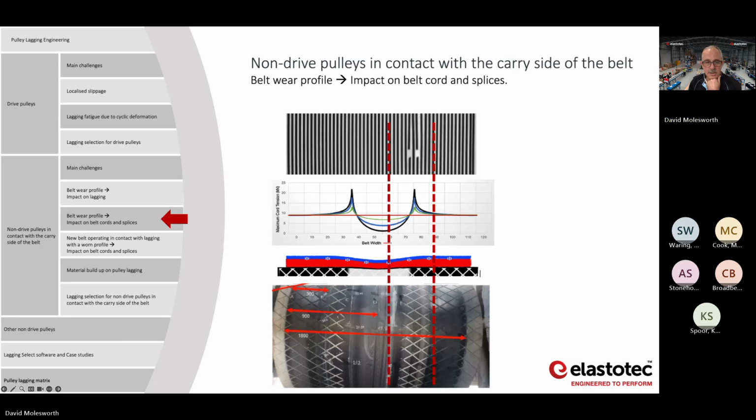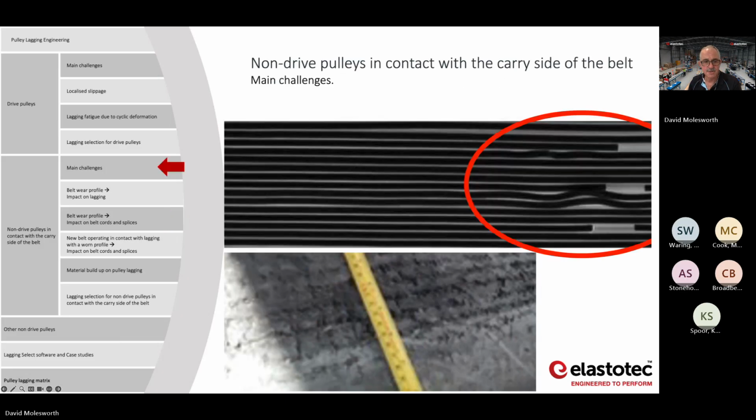Now, in a large majority of the cases, the damage and breakage to the cords lined up with the edge of this wear pattern. So the edge of the wear pattern is where we know we have the high shear stresses, and I'm just going to show you what we think is causing that. That's just another one of the X-rays where you can see the cords. These are cords that have been dislodged.